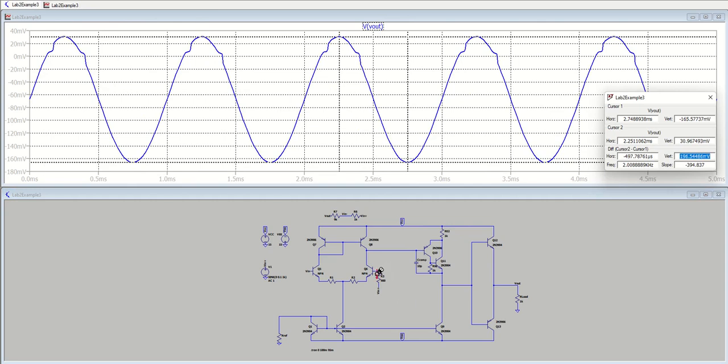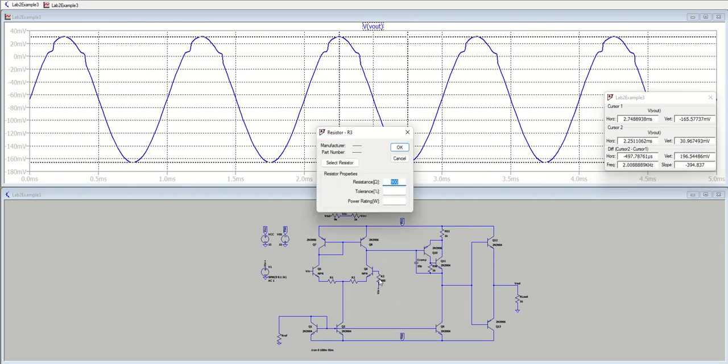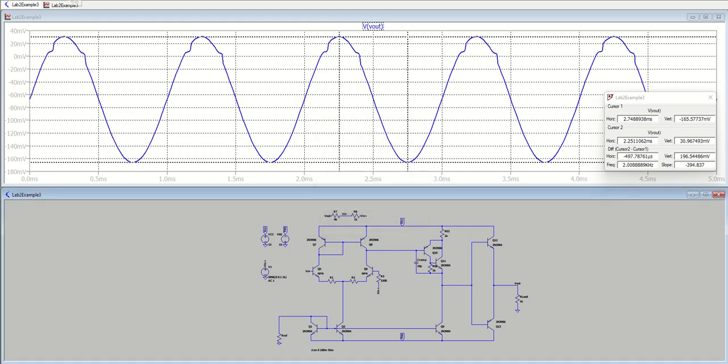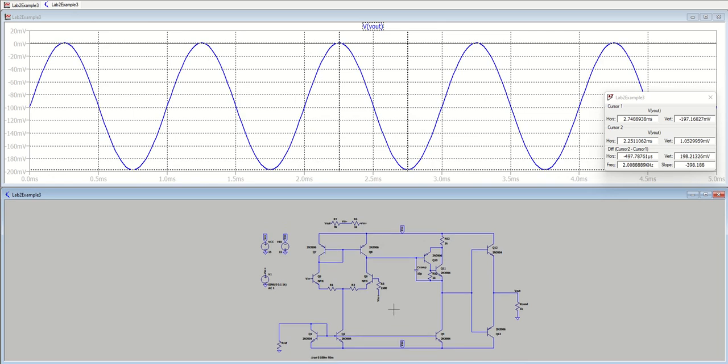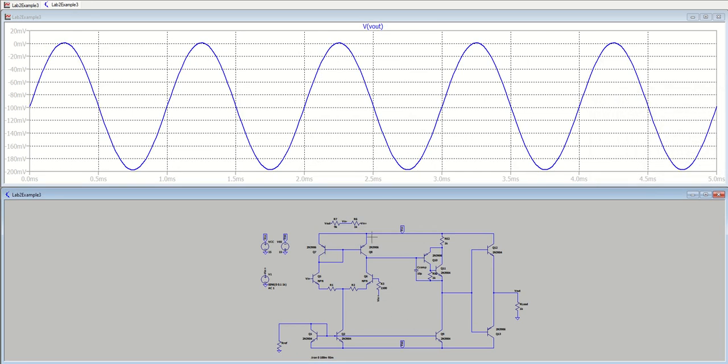And if we increase this value to a value that's past ideal, this value should increase. And it did. Okay, so we're able to determine that the compensating resistor does function properly. I think that there's just an issue with using a compensating resistor in the software to measure the DC component.